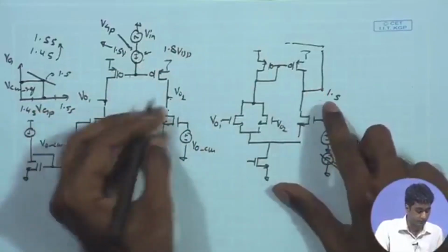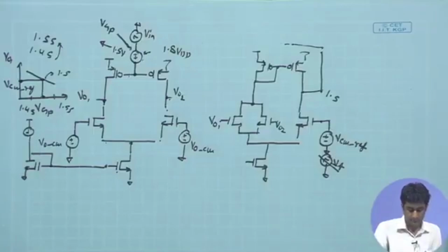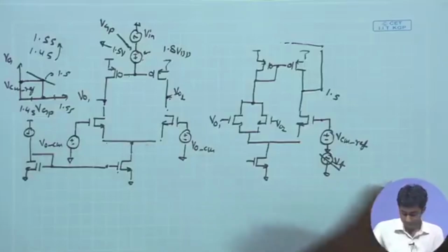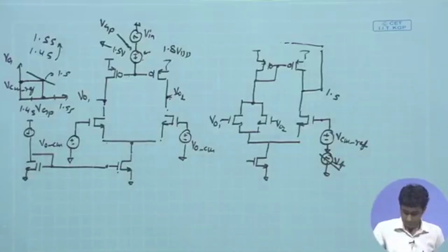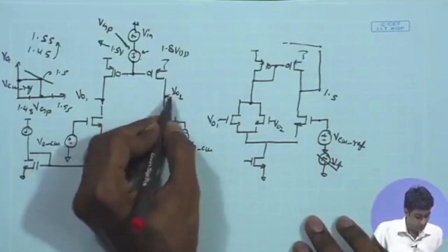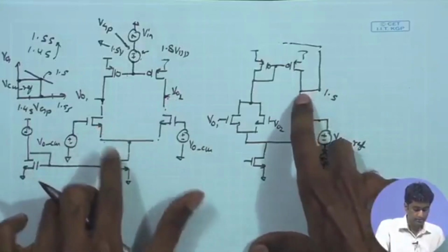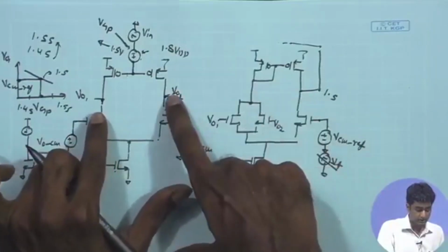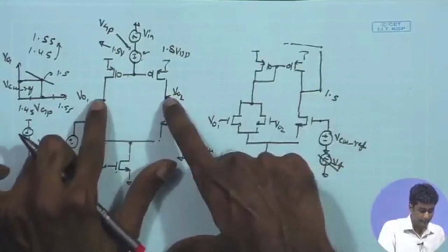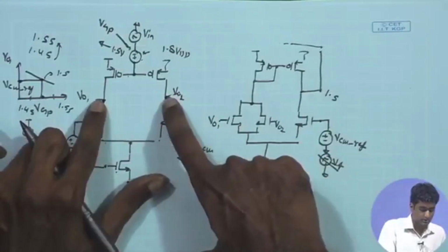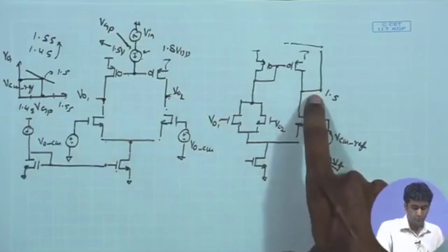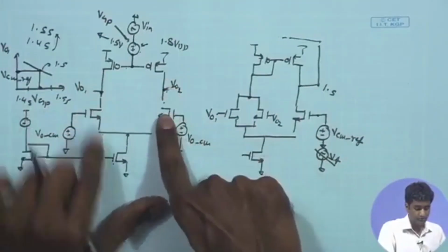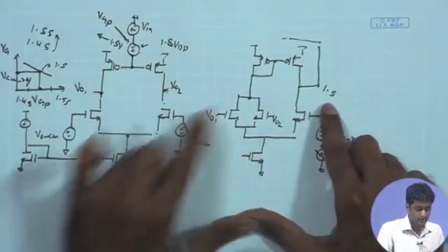So, in the compensation scheme, if you are using a cap between the outputs over here and the output at this point, that can lead to Miller multiplication between the input stage and the output over here, but that is however going to load the main amplifier also, which is not very advisable.